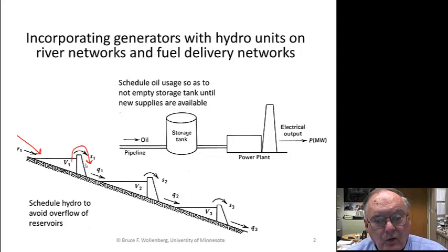We draw it here as being over the top. It's often the way it's done, although often the spillway is a constructed pathway that they build around the dam. Instead of over the top, it'll go around the side, but it's been constructed with cement, and it's reinforced and so forth, so that if the water gets too high, then there's a path for the water to get downhill so that it won't wreck the dam. You don't want it to ruin the impoundment here, the structure.